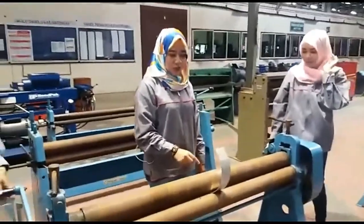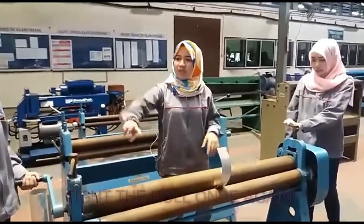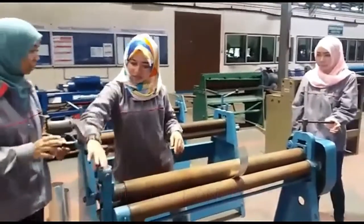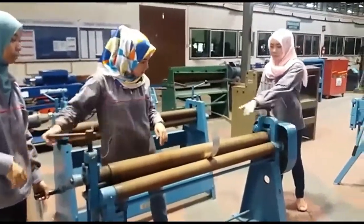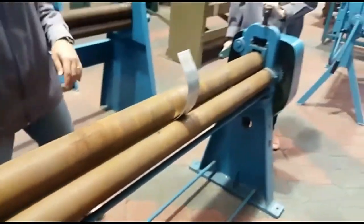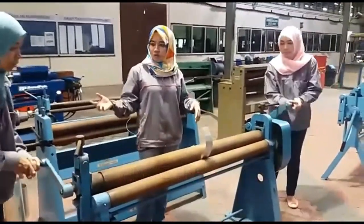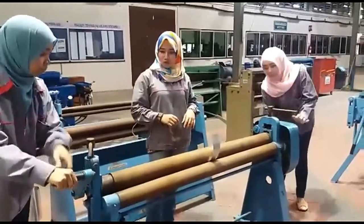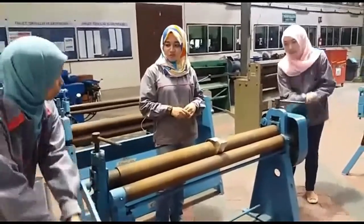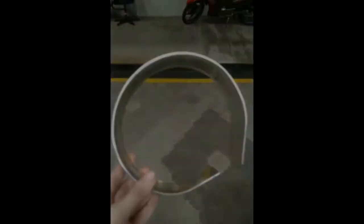After they finish on the sheet metal, operator 1 and operator 2 must tighten the upper roller. And the process will continue with operator 1 and operator 2 rolling the roll at the same time, in opposite directions. Then this is the product of the rolling machine.